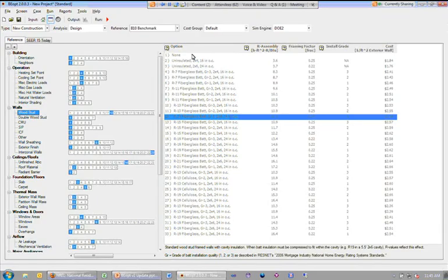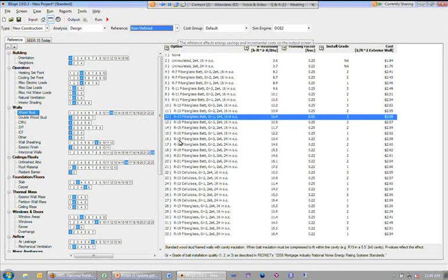Thanks, Craig. And in fact, that's a good segue into my next point, which is whether it's this automated reference or the min replace reference for retrofit, the two automated references. One thing that's nice in BEopt 2 is that now that I've selected the B10 benchmark, I could actually switch to user defined. Now everything is enabled. The selection is preserved relative to what the reference previously was. So now I can actually override certain aspects of the benchmark if I want to, but still retain the other pieces of the benchmark without having to go through category by category and select everything. That we think is a pretty nice capability.